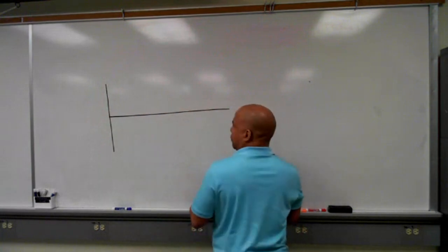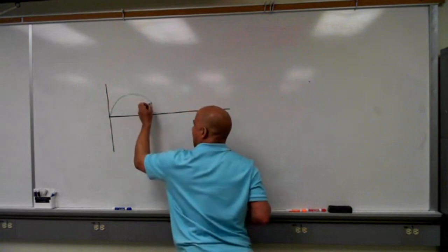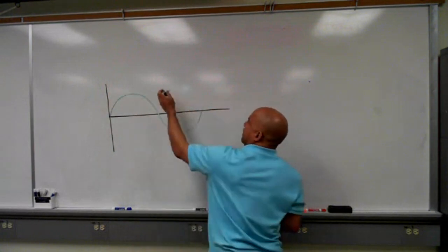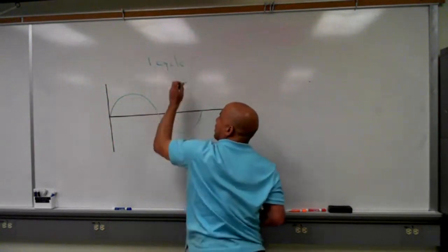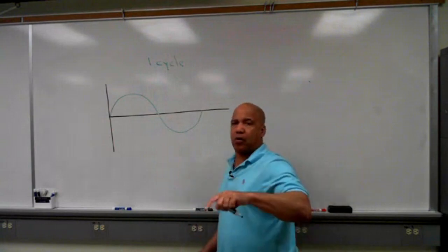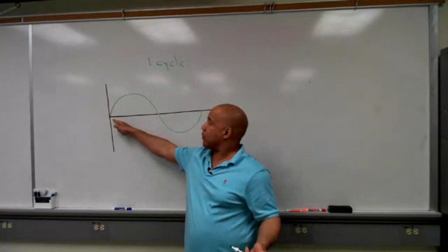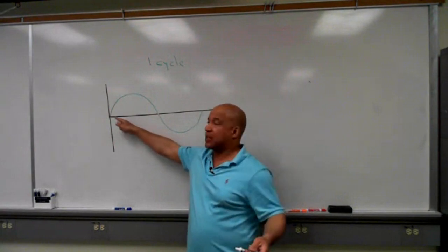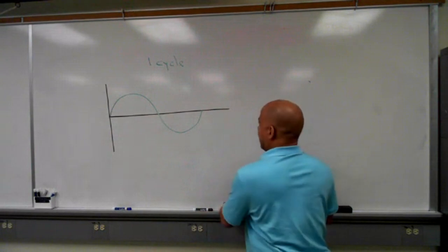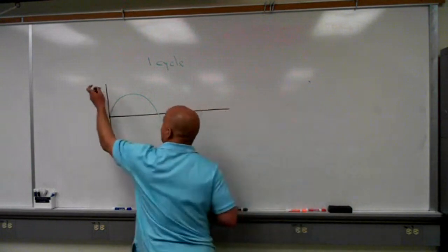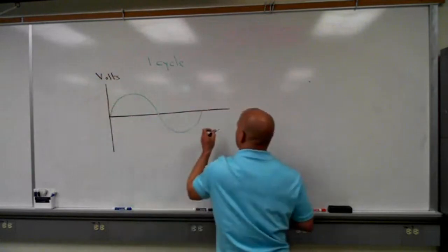And if I take this part, the sine waves continue on forever, but that's one cycle. So every time that generator coil goes around one time, it creates a voltage pulse or current pulse or wave that looks like this. We'll put voltage up there for now. I called it current last time, I'm going to call it V for now. So this is volts, and this is time.